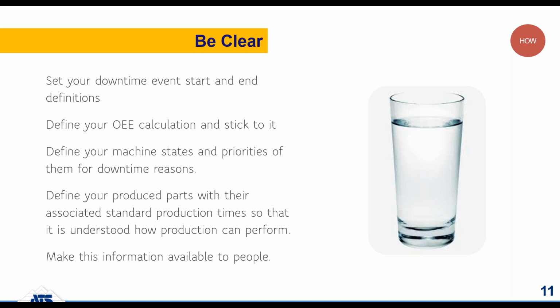So for instance, if a machine is faulted and starved, the faulted state should be given the higher priority and recorded against the machine, as that is the state that you want to identify as a real issue. If you are prioritizing your production scheduling, then perhaps you would prioritize starvation against machine fault.